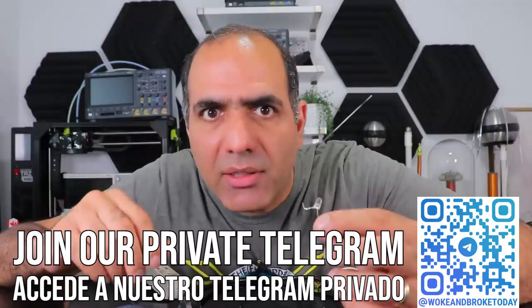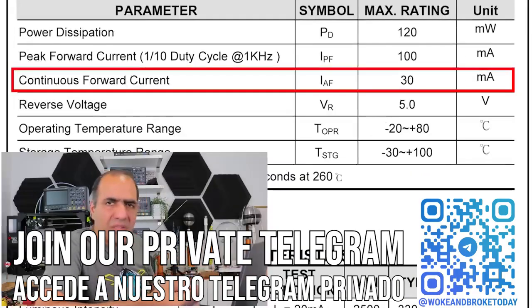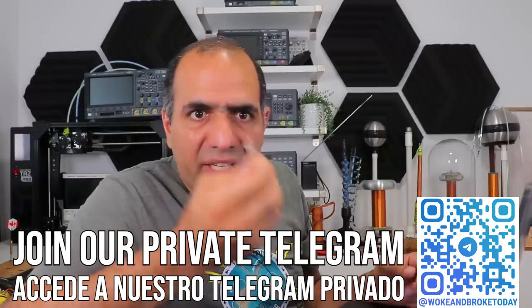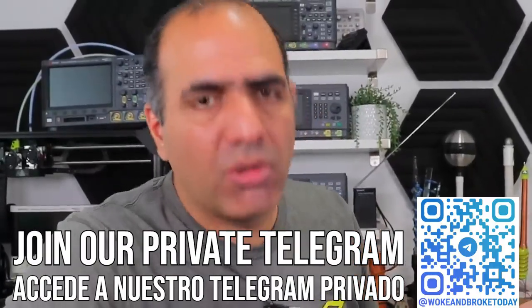So the LED blew for two reasons. The current was above its limit and the reverse voltage was above its limit. If you look at the datasheet of an LED, you see that for this one, the continuous forward current is 30 milliamps and the reverse voltage is 5 volts. If you don't put any limiting components on your LEDs, they are sure to die. Although not in spectacular ways.